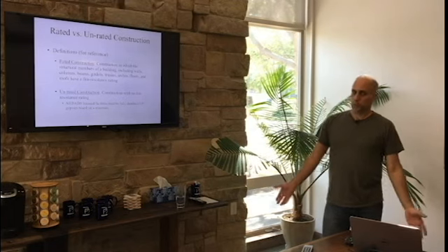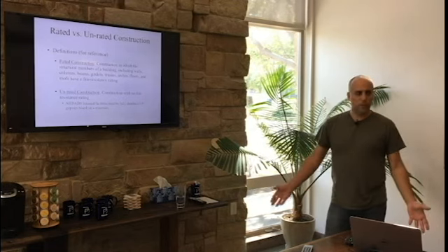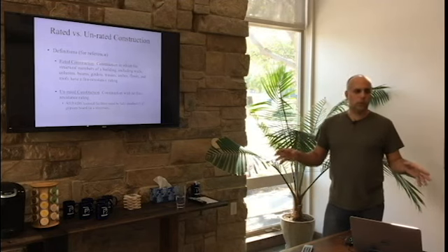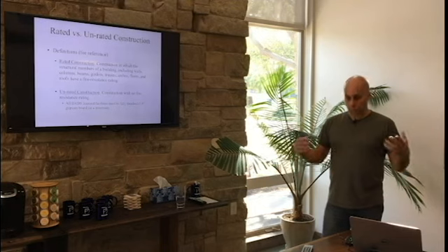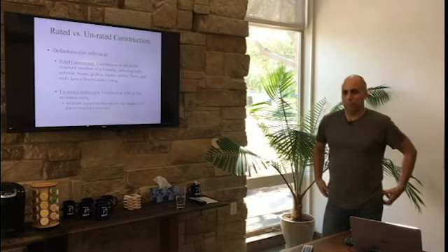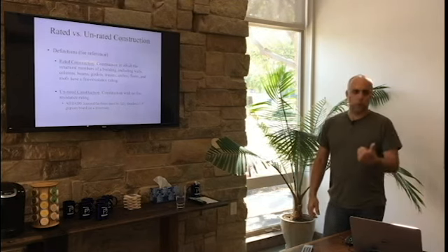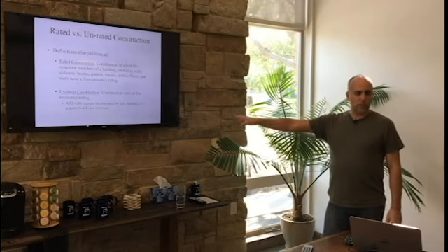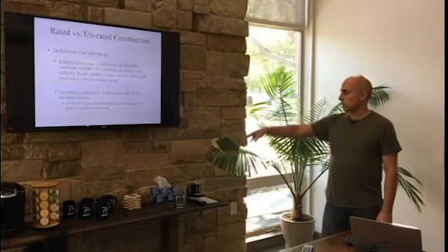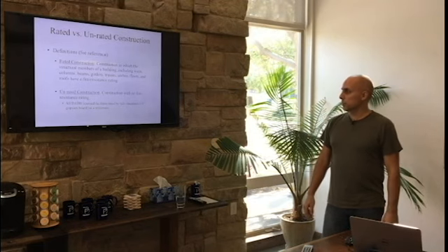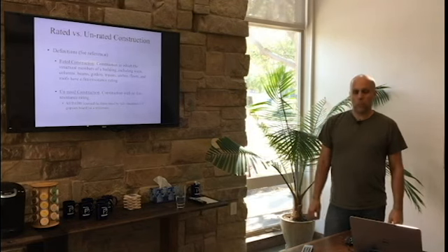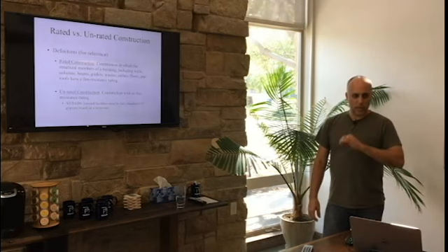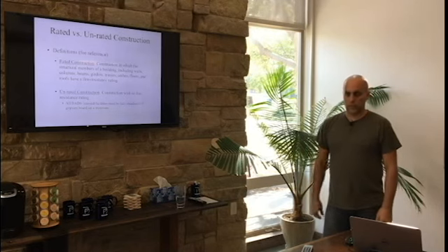Unrated construction, pretty straightforward. There's no rating. 0 hours on any structure whatsoever. The building will burn down very quickly if the fire is not suppressed by other means. For reference, all of DADS facilities, all the ones that are licensed in the state of Texas by the Department of Aging and Disability Services, must be fully sheathed, i.e. you cannot have exposed studs anywhere in a facility licensed by DADS.